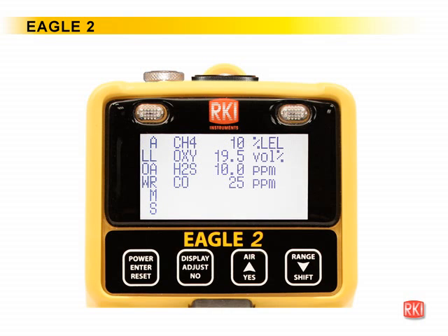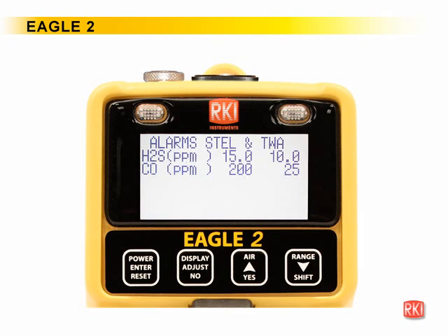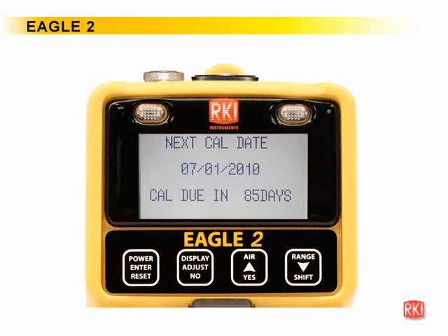The gas alarm set points are displayed by 3 screens in sequence: the low alarm screen, high alarm screen, and stale TWA alarm screen. Each screen remains on the LCD for 3 seconds. After the alarm screens, if Cal Reminder is turned on, the screen that appears next depends on how Cal Past Due Act is set in the Setup Mode menu.